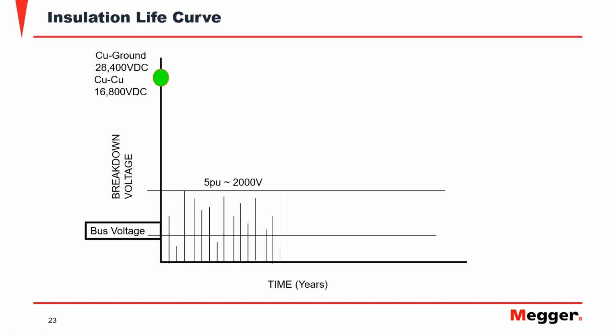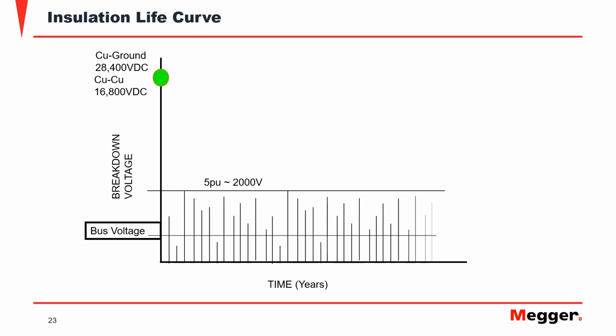Remember that through the life of the motor, it is continuously operating under conditions where it is seeing voltage spikes, and it's also seeing the conditions that we talked about before: thermal aging, chemical elements, contamination, aging of all kinds. That means that the breakdown voltage of the motor insulation is, little by little, lowering and getting lower and lower over time until two things happen.